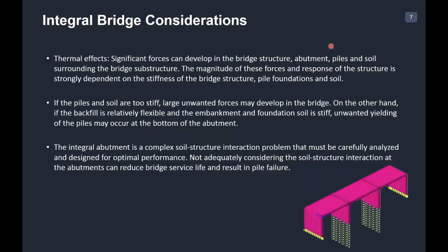Right, let's focus on integral bridge considerations. While you are doing the integral bridge modeling, what you need to take care of. First is your thermal effects. Significant forces can develop in the bridge structure because your deck is continuous and monolithic to the substructure, abutments, piles and soil surrounding the bridge structure.